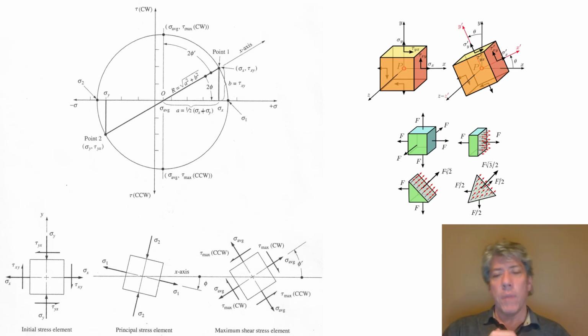Actually it is. If you imagine the cube, so look on the right hand side, that sort of orangish colored cube. We've got our cube sitting there with shear stresses and normal stresses on it, but this cube, the faces are cut matching however we arbitrarily decided to cut the part, whether it's a beam or a piston or whatever it happens to be. We've cut the thing in our minds in a very particular orientation, but that's arbitrary. The material doesn't care that we've imagined a cut face. What if we imagined a different cut face, a different angle for the cube essentially? We could still make up the part of an infinite number of these little cubes because they all shrink down to zero size, so that's no big deal.